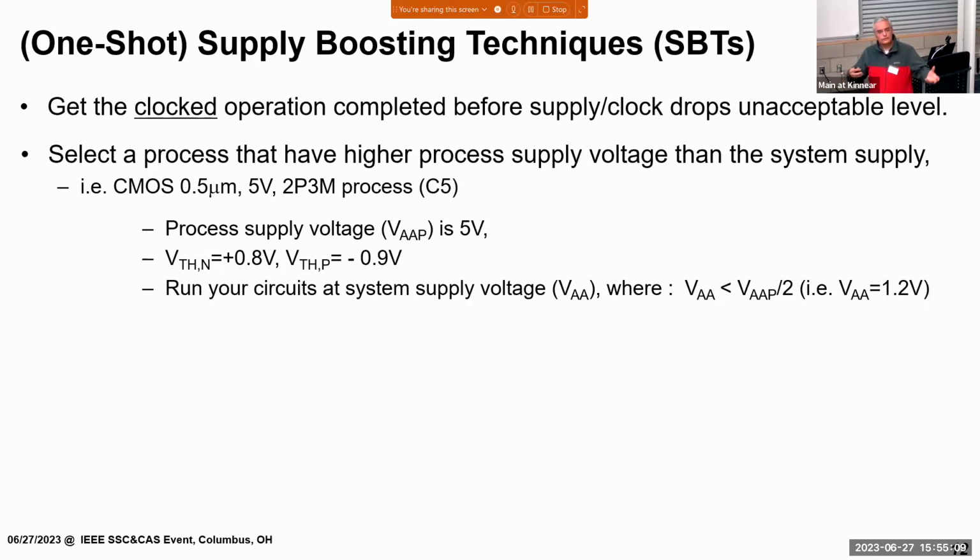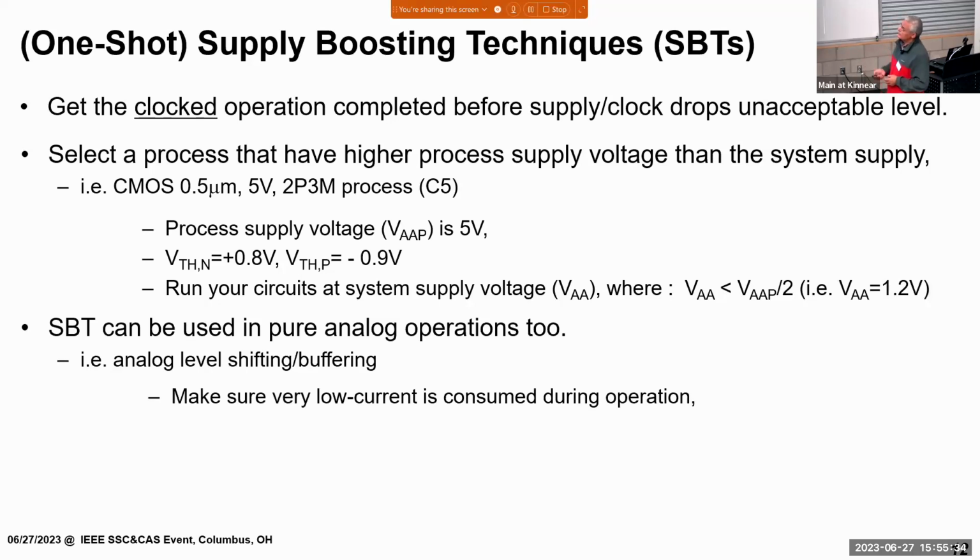Would the model support this? Is a question. Even the process guys may not really answer that question. They say, okay, we are giving you a 5-volt process, use the 5-volt supply. Don't go 10% up or down, we cannot guarantee. And their model may not really support that also. So you have to be very careful about the process that you are using and the simulation models that you are using in the design.